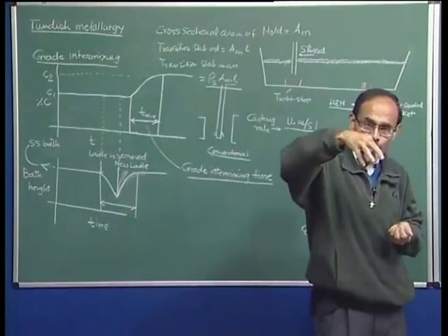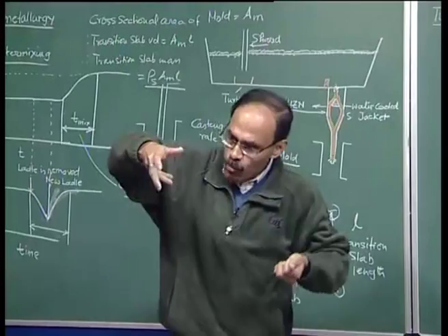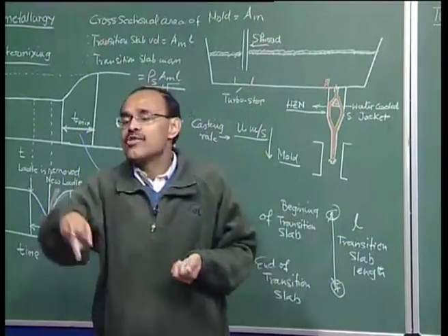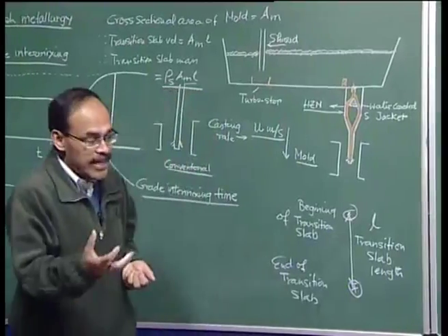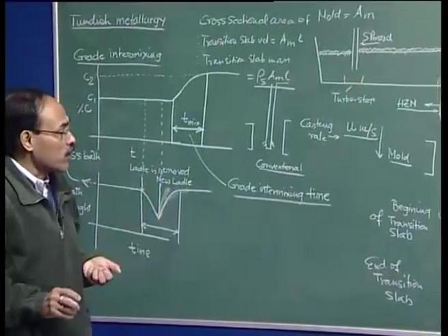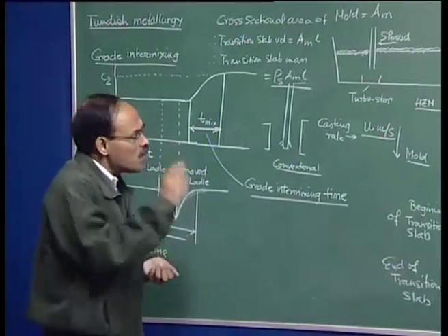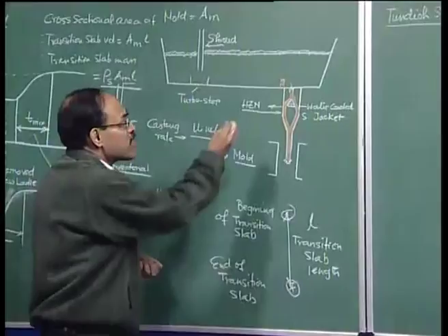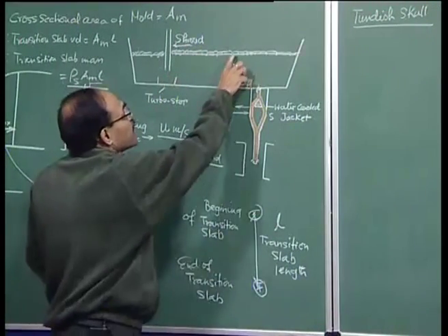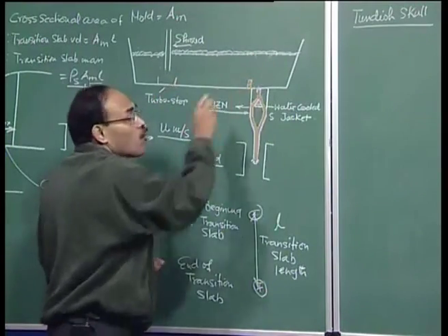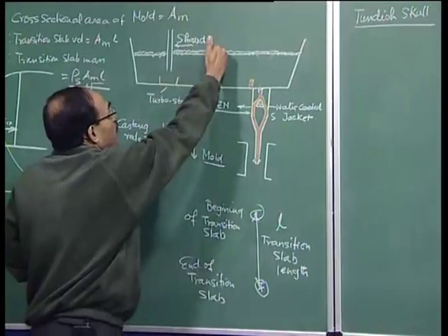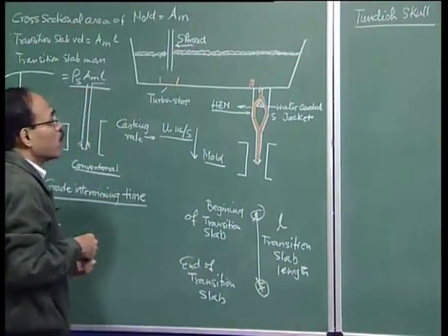You have kept the water open and the water is draining out, and the more the velocity of water from the tap, the more intense is going to be the tendency of creation of a rotational funnel vortex in the system. Similarly in the tundish also, as the flow rate, casting rate increases dramatically, there will be a tendency for the slag layer to be drawn, and particularly this is going to be prominent when we have the slag metal level going down.